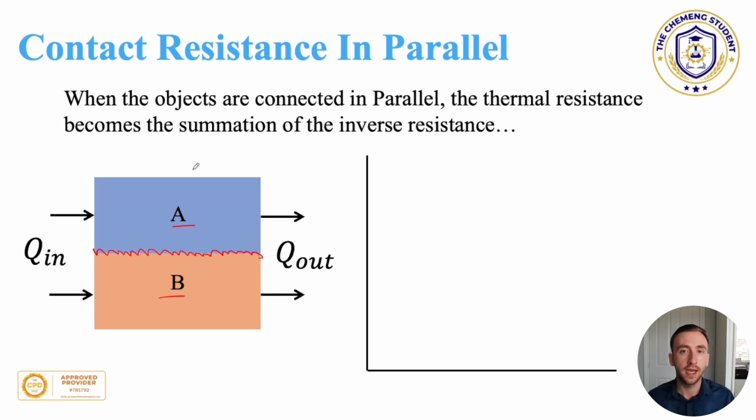Now, because the direction is the same for A and B, we will have some form of resistance because of the thermal conductivity of A, and some resistance for the thermal conductivity of B. Now, if these are different, then the change in the temperature profile will be different.